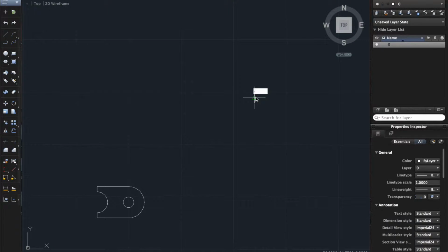We're going to do 0.75. That'll give us our circle. So that's our circle here. The reason why I used 0.75 is that all I did is click on the circle tool, go to my line, click once, and type in my measurement, and that gave me the circle I wanted.